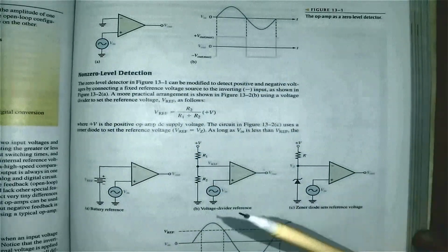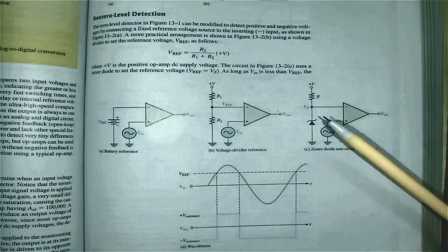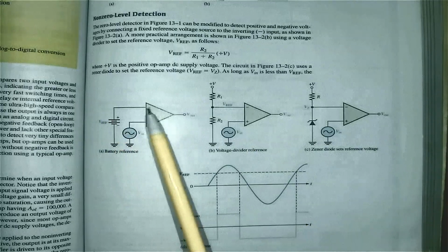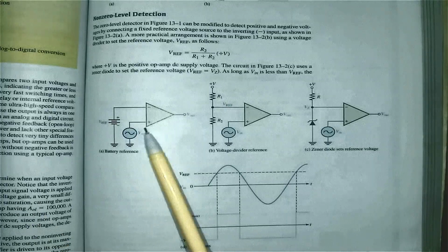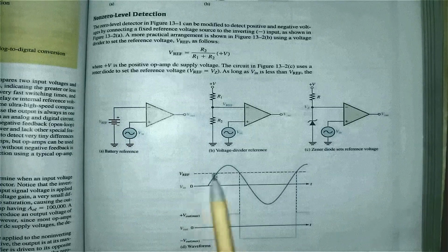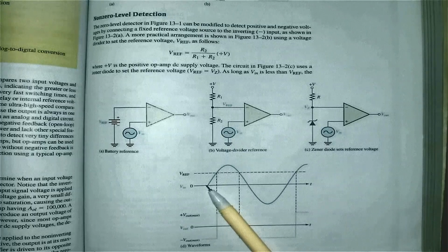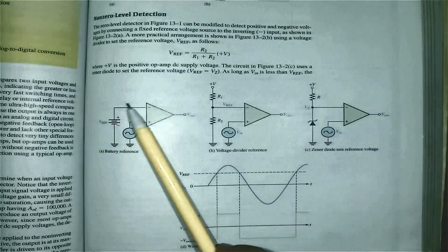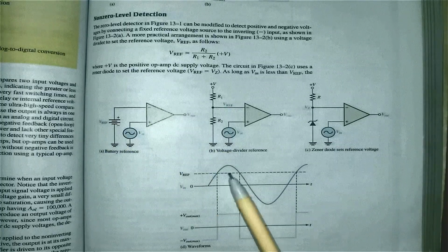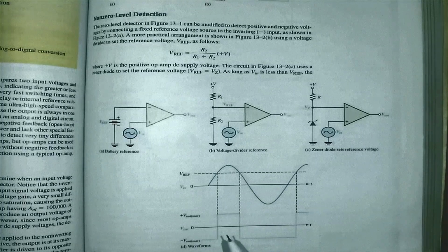Next, we're going to talk about non-zero level detectors. In this case, if we have a look, here I've got a positive voltage reference at my inverting input, and I'm going to compare that with my sine wave. Now my reference voltage there is positive. Now let's have a look. Here my input signal is 0 and my reference is positive. But where is my reference positive? At my inverting input. That means I'm going to invert positive.